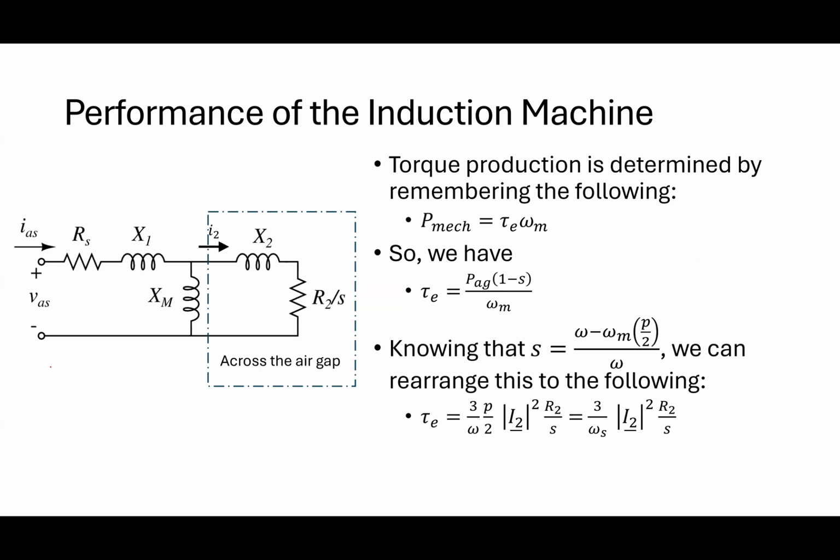All right. I think it's really important to us in all of these. We looked at a synchronous machine, induction machine, DC machine. In all cases, our circuit model had some reflection of what was happening in the mechanical side. For the DC machine, synchronous machine, it was somehow a voltage source, right? We had a speed-dependent voltage source. Here, I have this speed-dependent resistance. All right, that's happening. The reason we have that is because we don't really have an energy source on the rotor in the induction machine. How did the current get into the rotor on the induction machine?